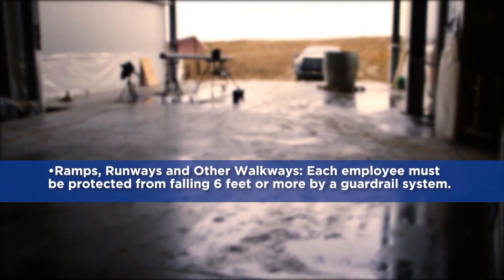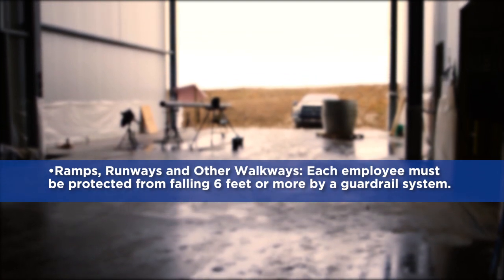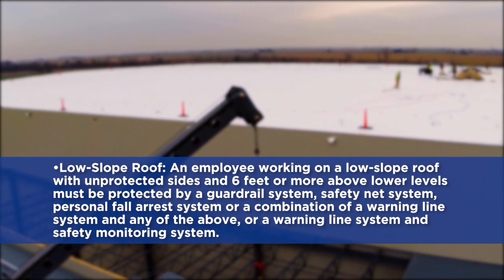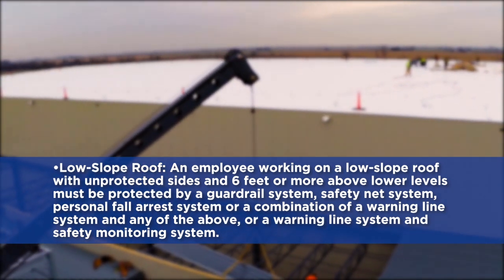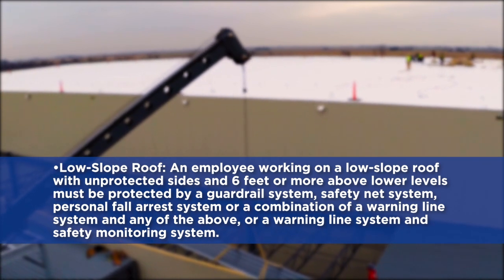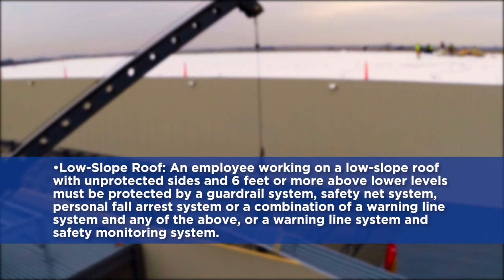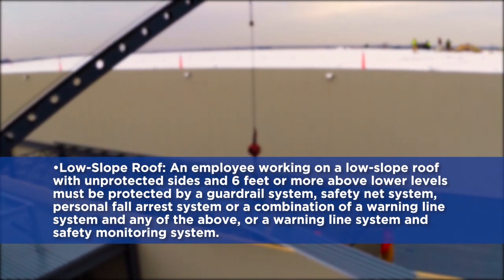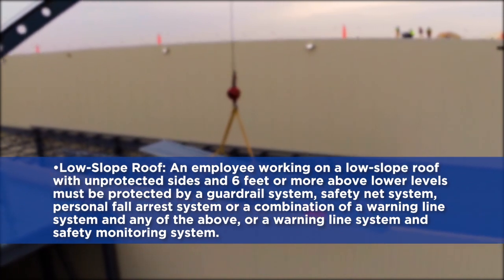Ramps, runways, and other walkways. Each employee must be protected from falling 6 feet or more by a guardrail system. Low slope roof. An employee working on a low slope roof with unprotected sides and 6 feet or more above lower levels must be protected by a guardrail system, safety net system, personal fall arrest system, or a combination of a warning line system and any of the above, or a warning line system and safety monitoring system.